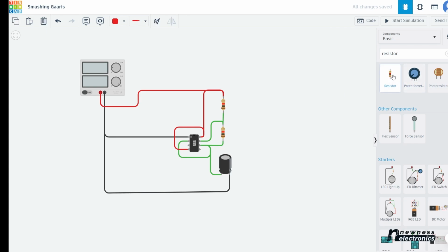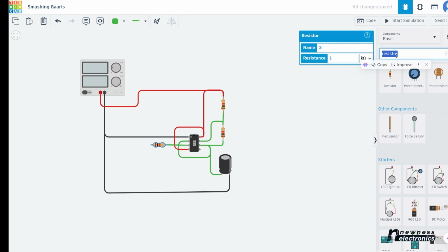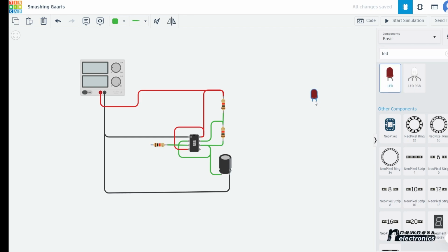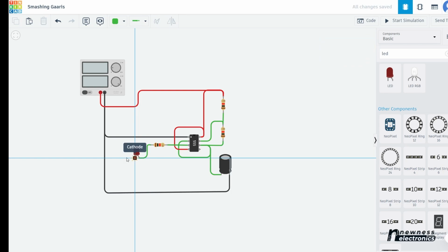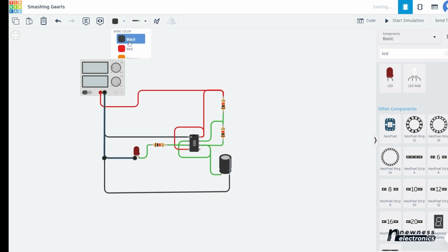Okay, so I need a resistor for that. Okay, we can connect it like this too. Change to green. And connect the light emitting diode to ground and change to black. Okay, so with this, we've completed the circuit for an Astable.